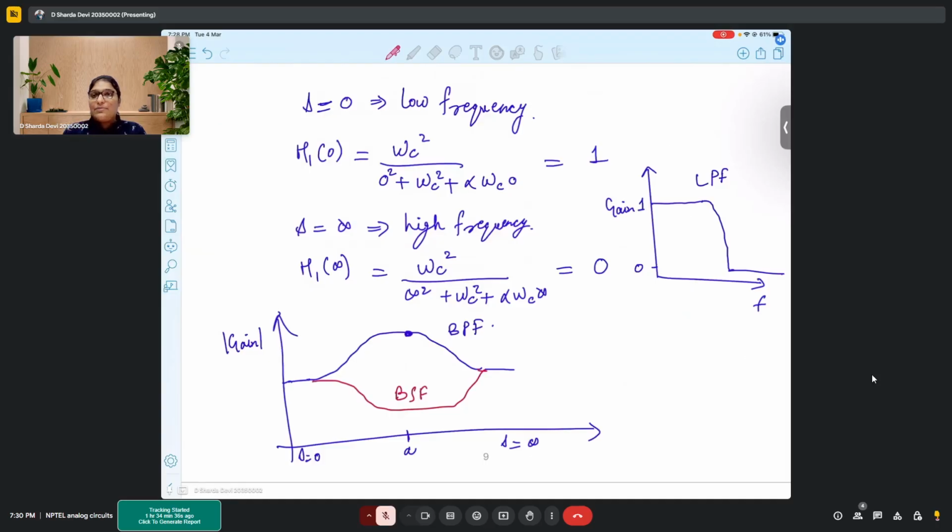Yes, this type of analysis comes handy when you have very complex circuits and very complex transfer functions, very high powered transfer functions, say s to the power 5 with 5 factors or 6 factors, a 6 order transfer function, 5 order transfer function. Now, sitting there and trying to get the factors out, factorizing the transfer functions, finding the poles and zeros, other than that, this is an easier way, right? Simply substitute 0 and infinite in S and simply see the values.